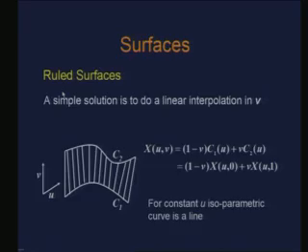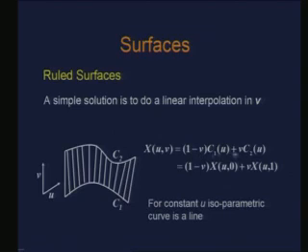That is what is being done here, and that is why we call the surface which is generated a ruled surface. So, all I am doing here is take this point and connect it to the other point of the boundary. It is just a traversal along the boundary curves or the contours, connecting the points for the same parameter value, which in turn means that I do a linear interpolation of the contours C1 and C2 in v.